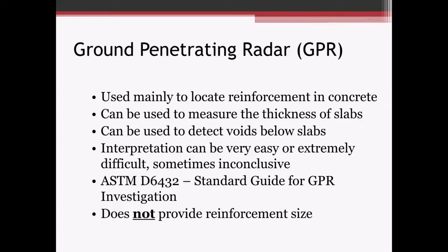We use ground penetrating radar specifically for concrete at very, very high frequency, 2600 megahertz, or 2.6 gigahertz. One thing to note: ground penetrating radar does not provide reinforcement size. There's not a GPR system on the market today that will provide reinforcement size, which is really unfortunate. My understanding is they're coming out with one, but to my knowledge there isn't one yet.